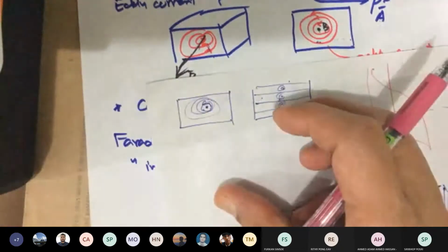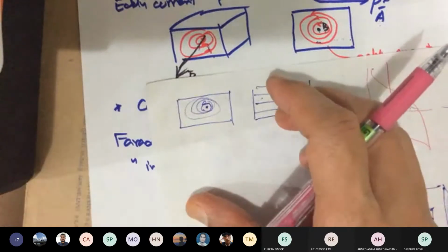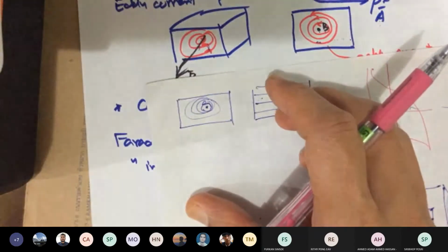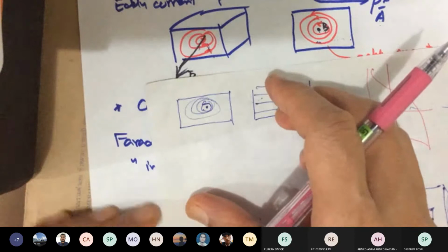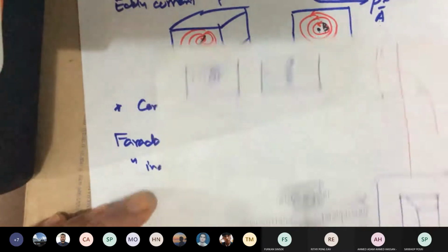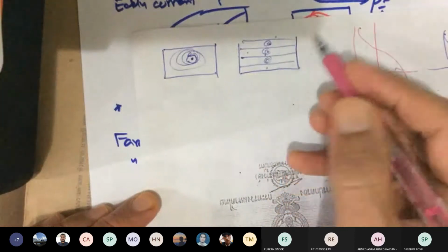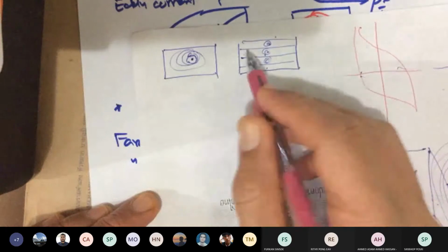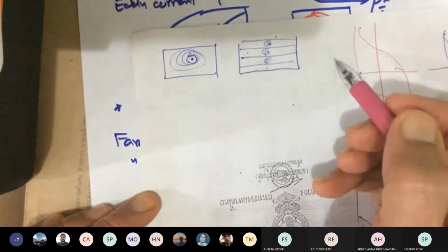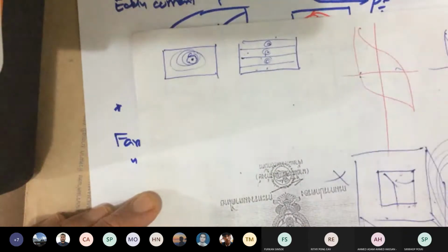That's why, like I said again, you will never see an electrical machine made from a bulk iron casing. The outside that you see is the casing, so that's not part of the core. Well, it's part of the machine, but it's not the one that produces the magnetic flux. If you open it up, you can image search, you see lamination cores. Even your textbook has a picture of that. It's always made of laminated steel or iron. These are the reasons to reduce the core losses.